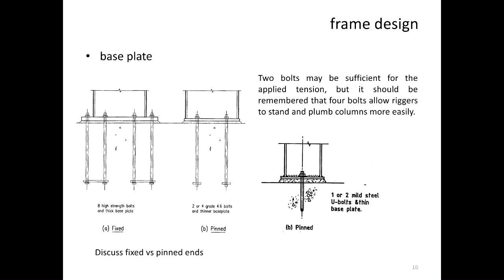Correct. Because why? If I put that directly here, and then it's not plumb, what happens? It's not vertical. Then you're in trouble. So that is why the design will be to have packers underneath the base plate. So there will be packers under there, maybe rounded, like shims, but rounded ones, which sit over the threaded rods, and then that is used to adjust the verticality of the column, and then you put a non-shrinking grout under the base plate.